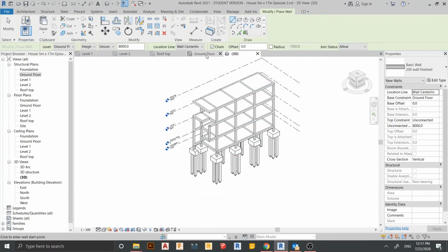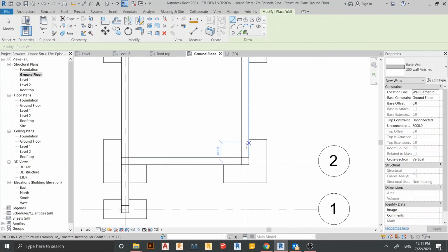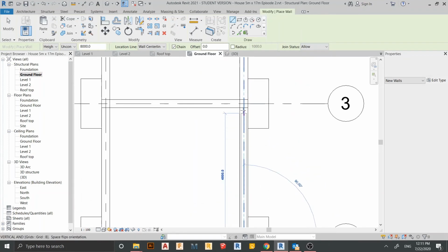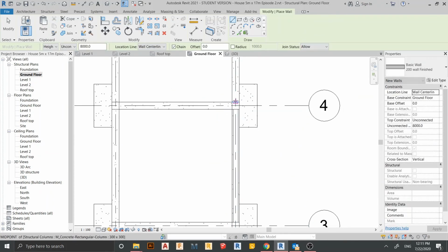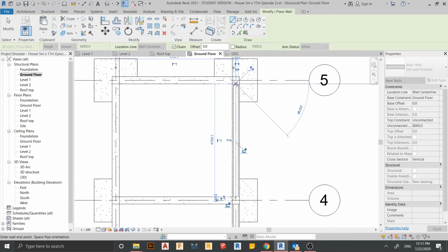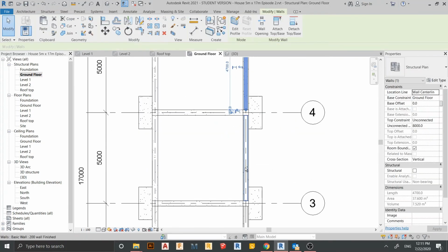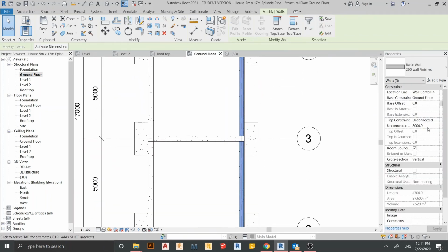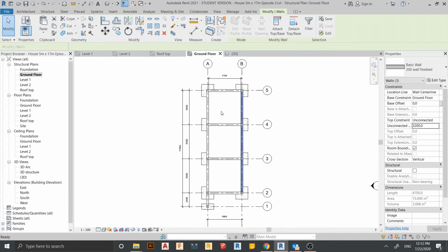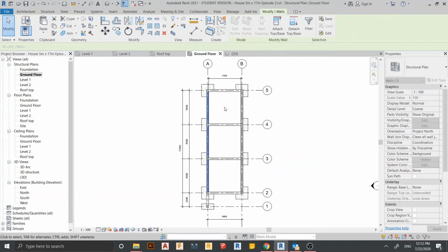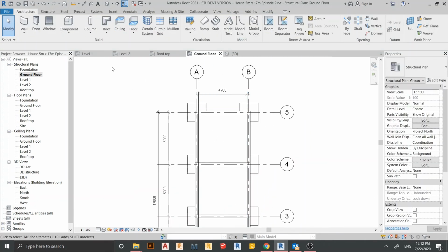Let's draw our wall. I'm starting from here for my ground here. Okay, so like this 1, 2, 3. We change the height to 3200 and then hit apply. Then I'm going to press DM on my keyboard for draw mirror, find a center line like this, go into our, okay, so I just close here for WT on my keyboard for window tile.